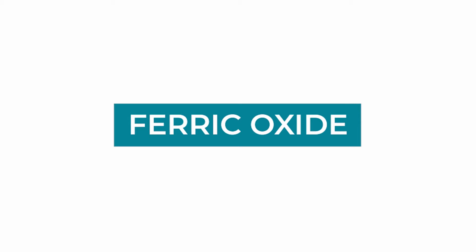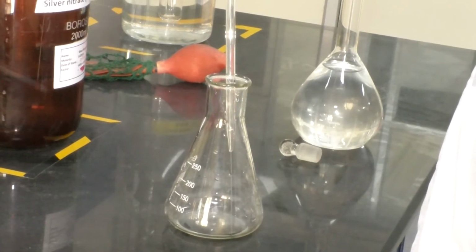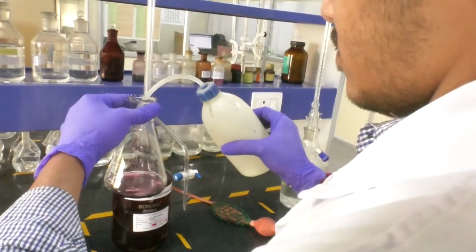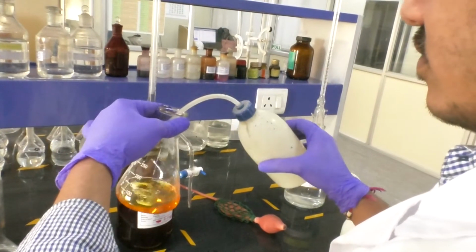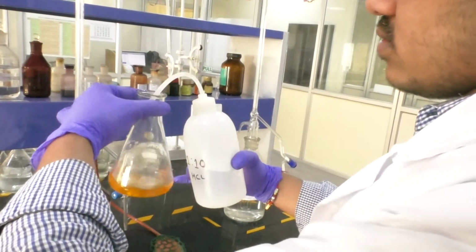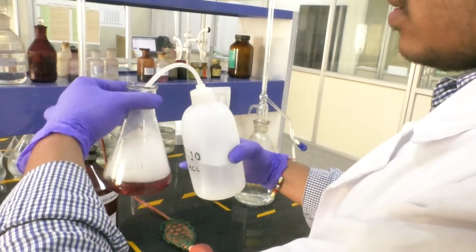Ferric oxide. To determine the ferric oxide, take 25 ml of solution preserved as silica filtrate in 500 ml conical flask. Add sulfosalicylic acid and 1:6 ratio of ammonium hydroxide till color changes to yellow. Then add 1:10 ratio of hydrochloric acid up to color change to wine red at pH 1 to 1.5 approximately.